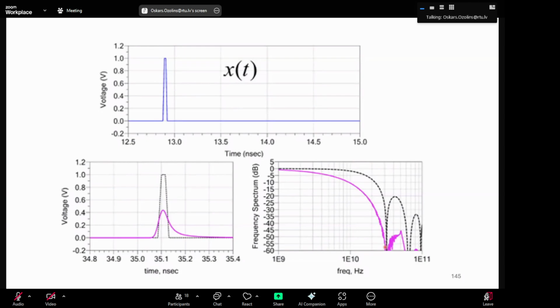at a specific wavelength, like C-band 1550 nanometers, where the dispersion is 16 picoseconds per nanometer per kilometer, and then you use a square law detector. Then the bandwidth can get smaller depending on how long the fiber is, or how much dispersion there is in the system. So that's another effect which limits the choice of wavelength for these transmitters, and also the choice of equalization that you can do.